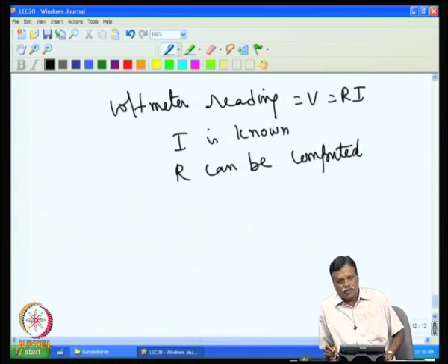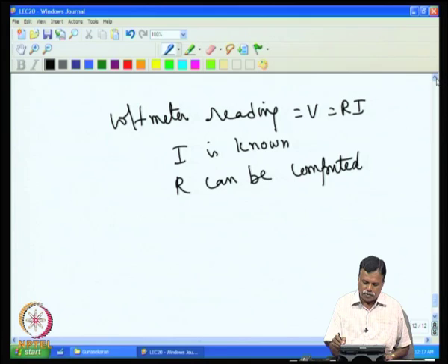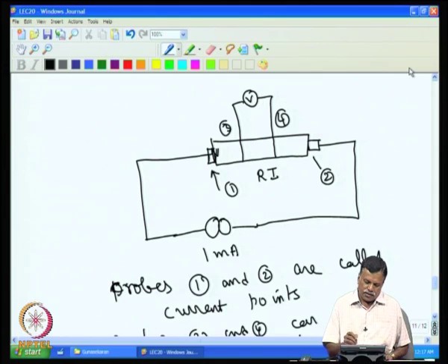Now, that is about the measurement. But the question is why this method is accurate and why the contact resistance is not a problem. If you look at the circuit, the voltage that comes here only depends on the resistance between these 2 points. Whatever resistance is added at the current contacts does not matter, because the current remains constant, since it is a constant current source. The current is always adjusted to 1 milliampere. So, these resistances have no effect on the measurement.